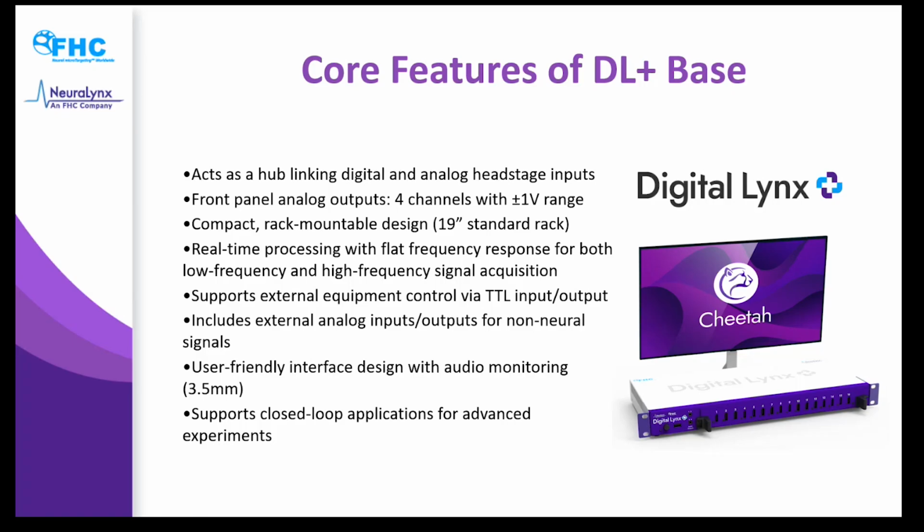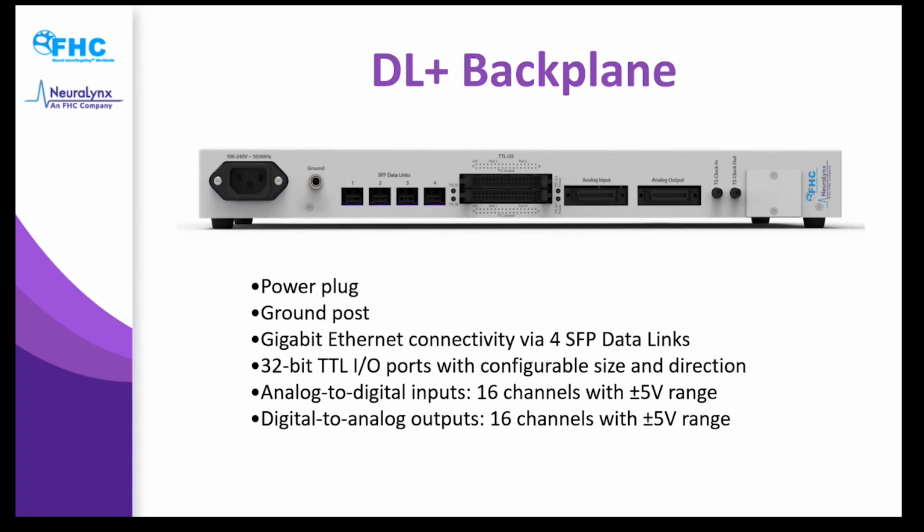So some of the core features of it are on the front panel. We have analog outputs. This is an increase from the SX to have more availability for customers to bring in analog inputs from other devices. We continue to have the real-time processing for both low frequency and high frequency signal acquisition. Continue to have TTL input and output to support external equipment. We also continue to have the audio monitoring, and then we still have the support for closed loop applications through outside software, typically MATLAB.